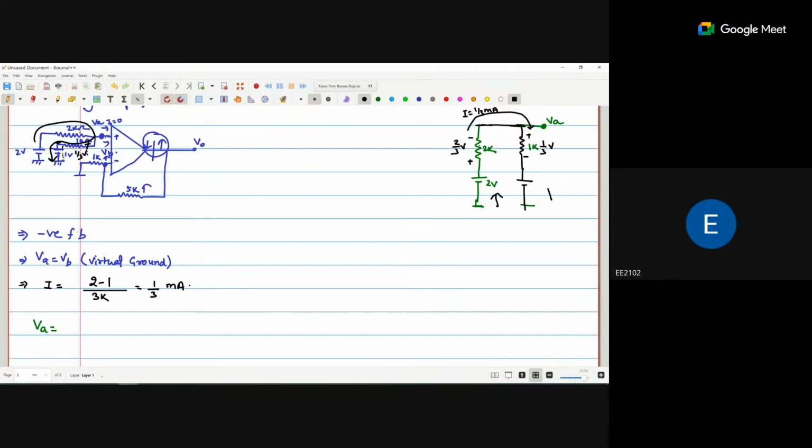Okay, why did I mention the positive and negative sign in this way? Because of the direction of current. Current will enter at the positive, higher potential, and current will leave at the lower potential. So the direction of current is 2 volt to 1 volt. So that means the current is entering here and it will be leaving in this direction. So this one is the positive, this is the negative. The current is entering from the top and it will be going to the bottom. So it will be the positive and this one is the negative. Okay, any doubt? Yes, no? No, sir. Okay.